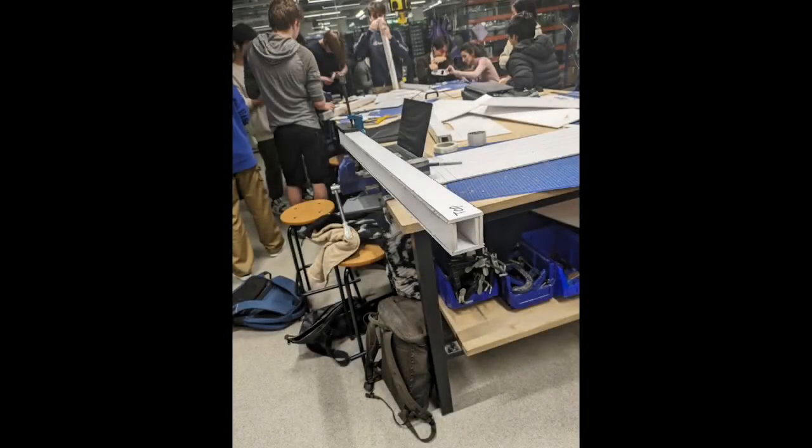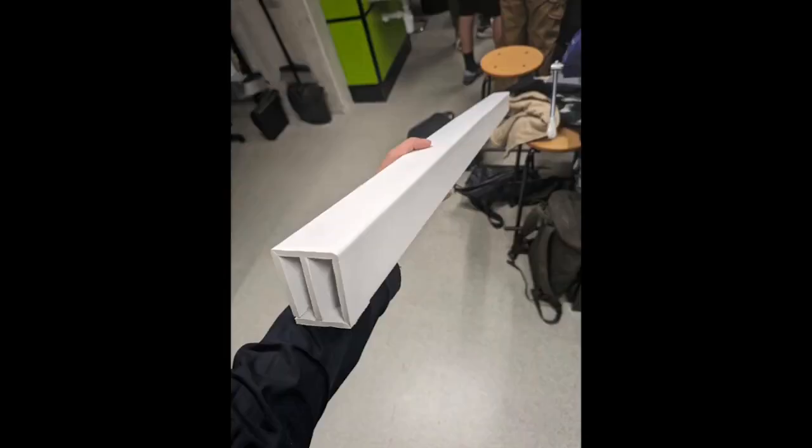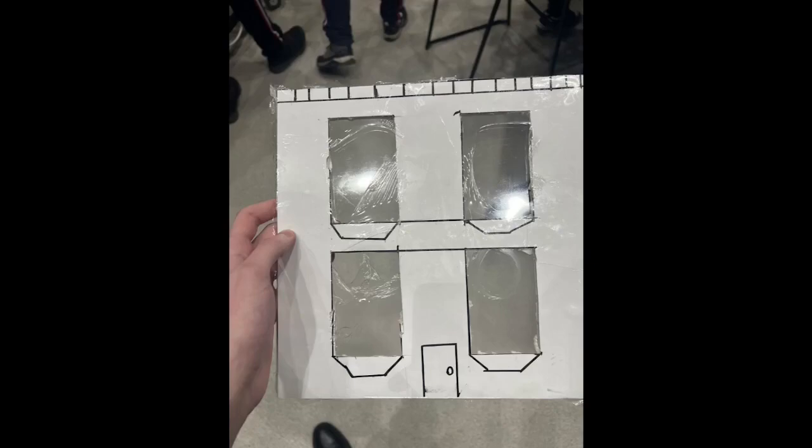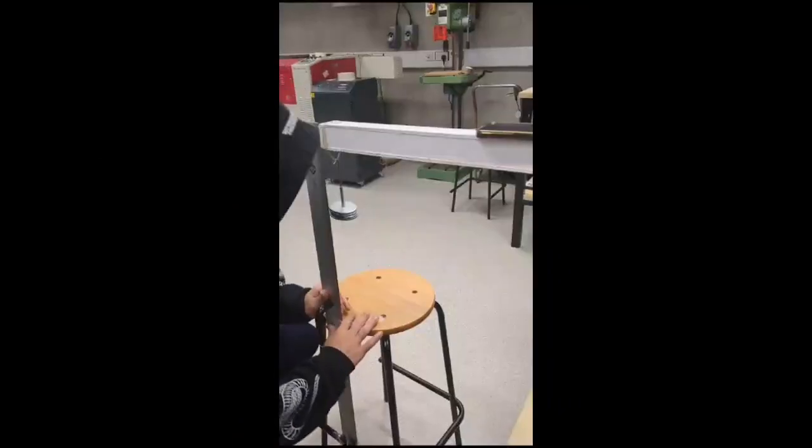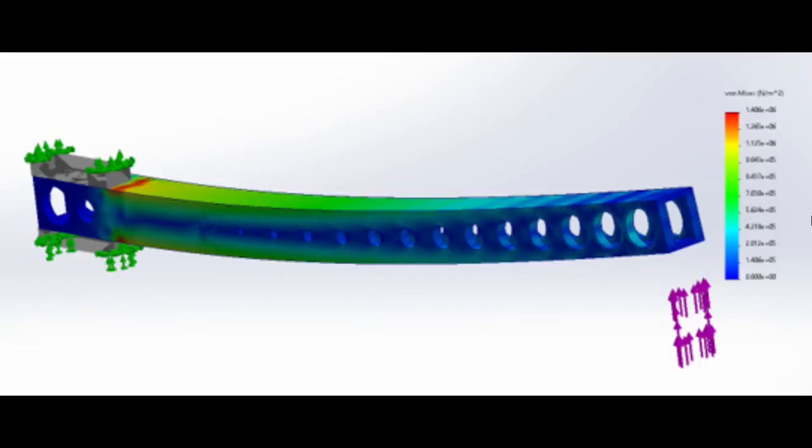The practical work in the lab sessions was the catalyst to the completion of our spar design, but in order to create our perfected spar, we went through many failed attempts and iterations. These iterations were important in optimizing our wing spar in order to meet all design requirements. In conclusion, after starting with a preliminary design for a wing spar, we settled on a final design after testing, whereby we maximized the amount of material where the highest shear force would be located.